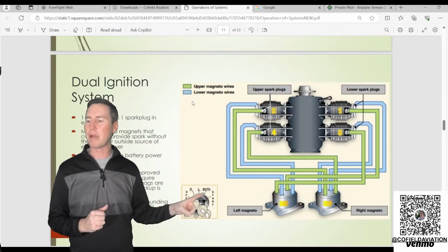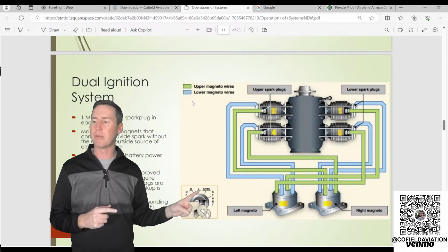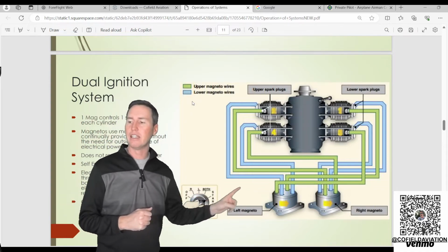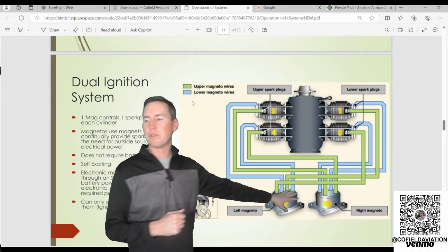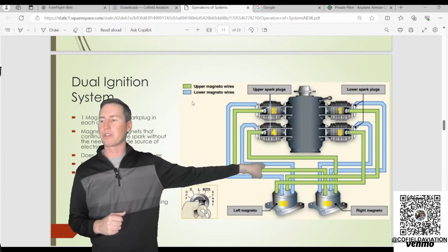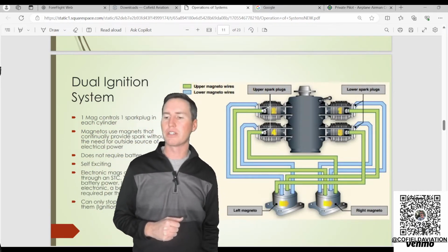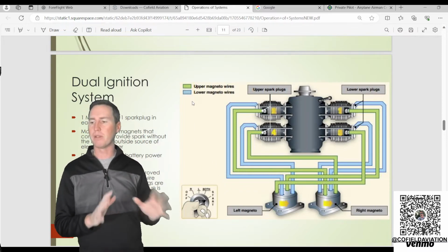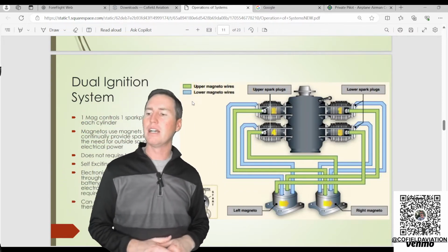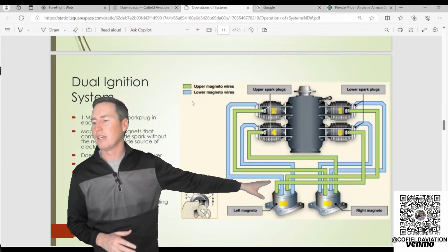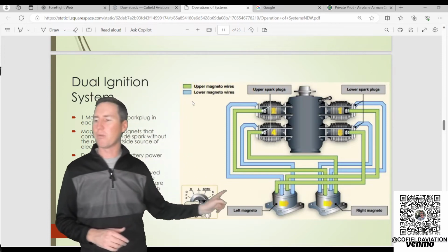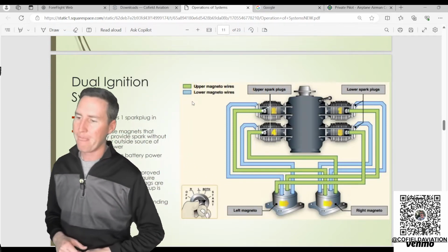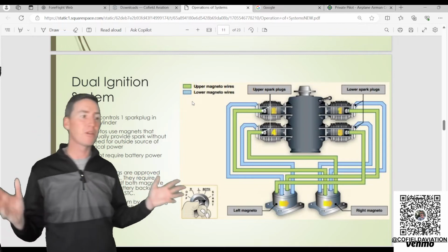And then we go back to both. We should get that rise. We go to the left mag, and then we're operating on the left. We've turned the right mag off, so we're making sure the engine runs just fine, no more than a 100 or 150 RPM drop, 50 RPM differential between the two mags, just making sure that works fine, and then we go back to both. So there's our redundancy in the fire, pretty simple.